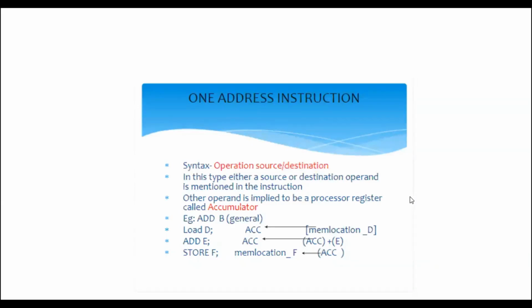Whereas in one address instruction, it has only two fields. It has one field for opcode and one field for address, while it has a shorter instruction length and it is faster accessing a location inside the processor than memory. It generally needs one memory access.